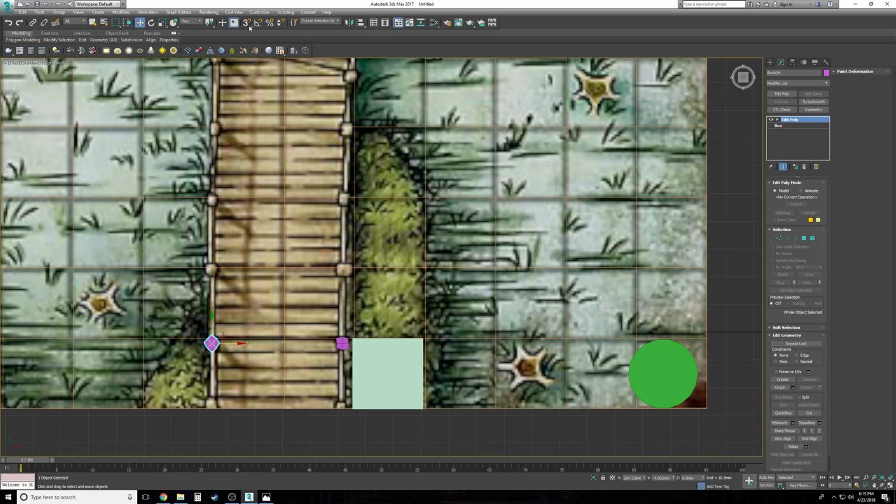This is the one time I don't have my snap angle tool right here. That'll rotate the thing in increments so that you have more finite control in your rotations. But right there, I just rotated it randomly because I don't want consistency. Make a copy here. Make sure it's still instanced. Actually, before we start doing that craziness, we need to keep track of our naming systems. We have it as box 001, and we're going to make a whole bunch of these.